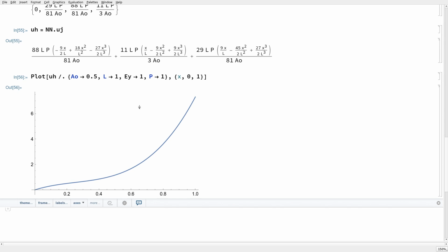It can describe elasticity in a bar. It can describe steady state heat conduction. It can describe steady state pressure diffusion. It's all the same physics. Depending on the choice of the coefficients A, C, and F, if you apply those to the different physics, then this one method that we've described here will solve all of those problems.